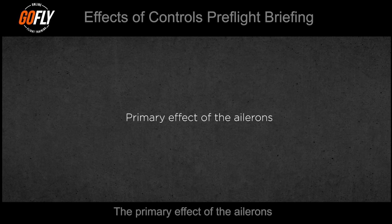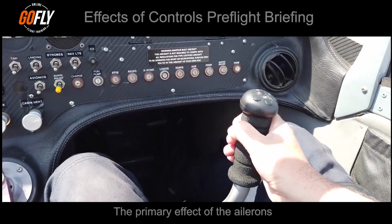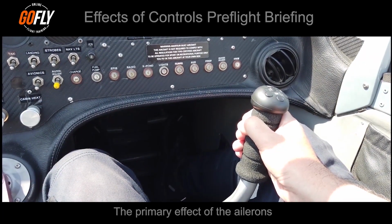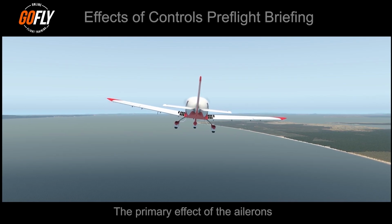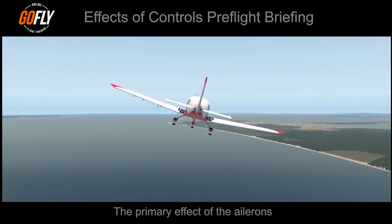I will now demonstrate the primary effect of the ailerons. When we move the control column to the right, the left aileron moves down, causing a force upward, and the right aileron moves up, causing a force downward. This causes the aircraft to roll to the right.